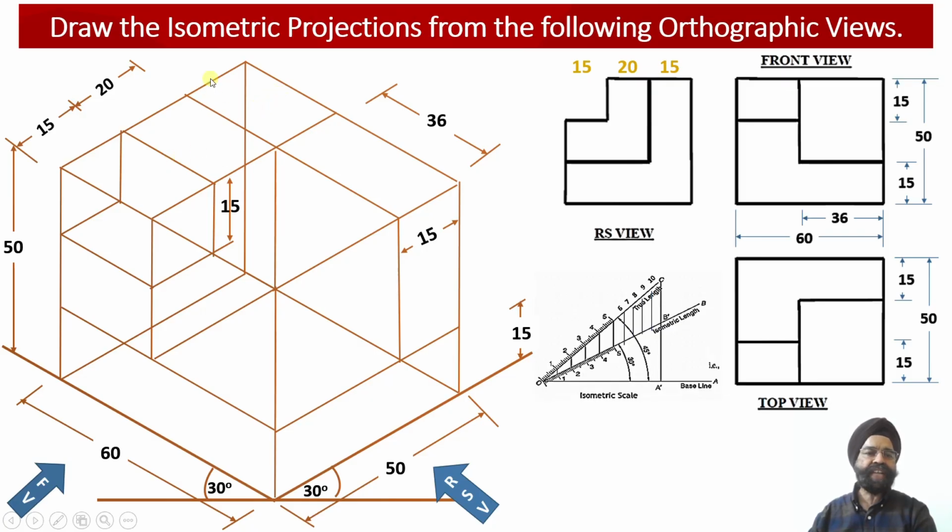side of the solid, such that the width of this web happens to be 24 millimeter, and at a distance of 35 millimeter from the rear side, it has encountered an intersection with the cutting plane in such a way that we have got a step over here in the downward direction, where the height happens to be 15 millimeter and the width of the step also happens to be equal to 15 millimeter. And now from this point a vertical projector we draw, and from this point again we draw a projector.